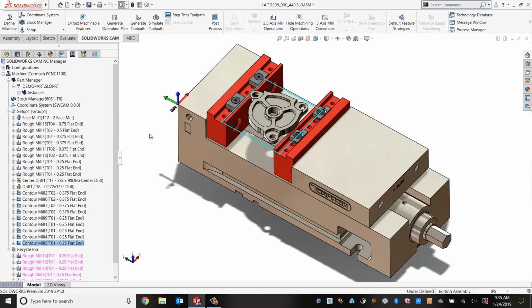The majority of the time when you run SolidWorks CAM, it's not going to give you a production ready program with 3 simple clicks. But it'll get you 85–90% of the way there, and from there it's just a matter of tweaking what you're doing and getting it dialed in really. It saves a lot of the monotonous day-to-day operations of doing every individual program by hand, and that chews up your time and also invites human error.